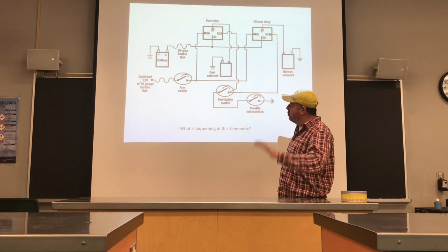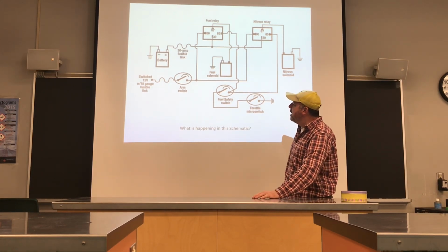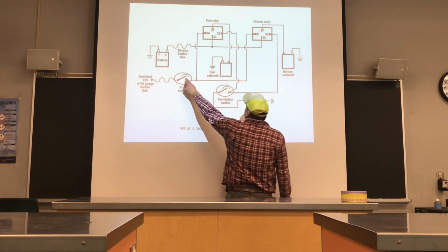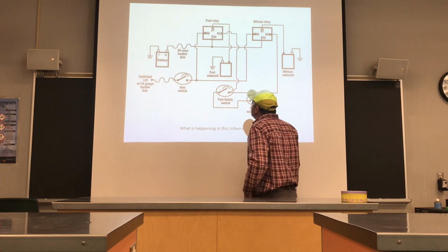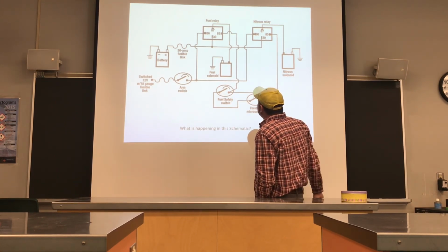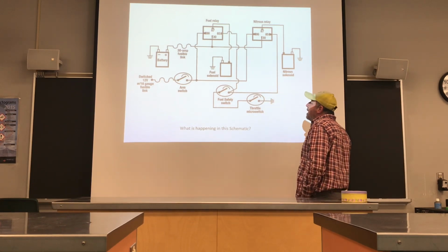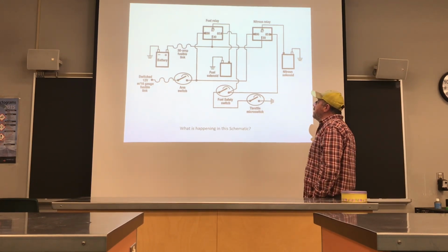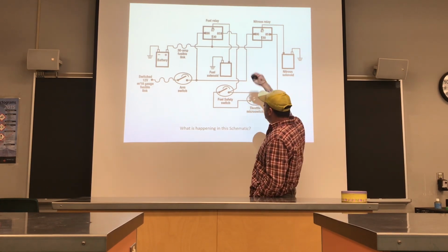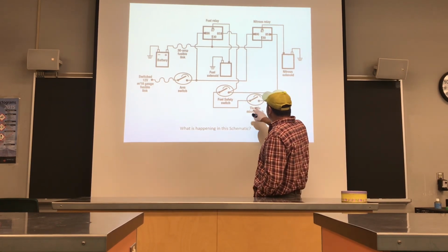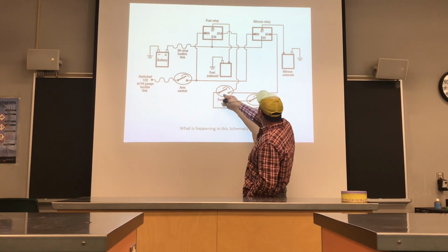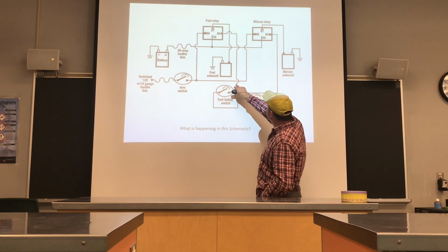So we're going to put the arm rest down, or the safety switch. We're going to close that. It's going to supply power to pin 86 on both. So there we have power at the coil. We're ready to make each relay function as soon as we close the ground side of the relays.